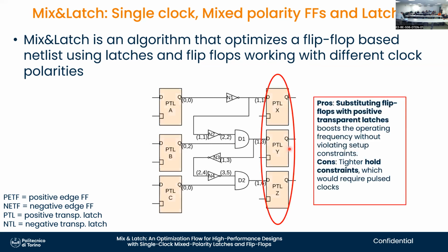So the first thing we do is convert all the flip-flops into positive transparent latches. And as we saw before, this is good because it allows you to borrow time, because this is going to be open for a certain amount of time, not just when you walk in and go out. So there is not a strict timing constraint about when data have to have arrived here. It can be early, and then you have more time for computing on this side. Or it could be late, and then you can have less time to compute here, and you can balance things much more evenly.